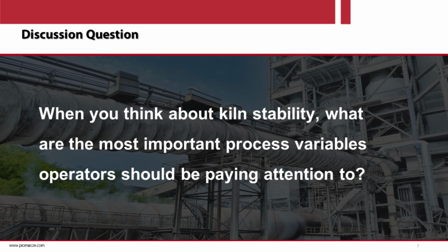But I would like to say that if you are able to measure the flow at the preheater, close to your ID fan, and at the tertiary air duct, you will have a more reliable picture about the heat balance and where the flow is actually going.